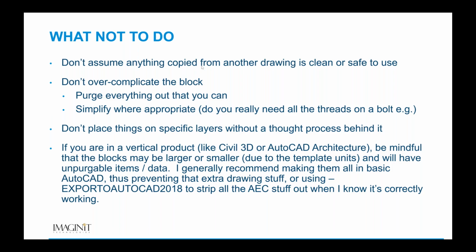This is why I say whenever possible, put everything on layer 0. If you just turn layer 0 or the A-building layer off, the block will still stay there, it will still be visible. But just understand there are things like that.